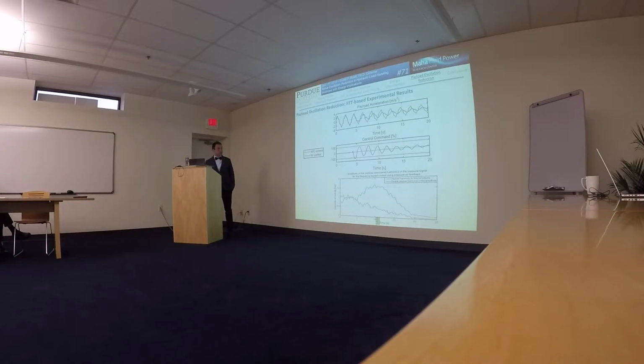Once the controller starts, the red line decreases in the same way the payload acceleration decreases. But the blue line, at the same frequency as the payload, actually increases and then decreases. This is exactly why we cannot use this frequency: the controller is actually affecting this pressure information.